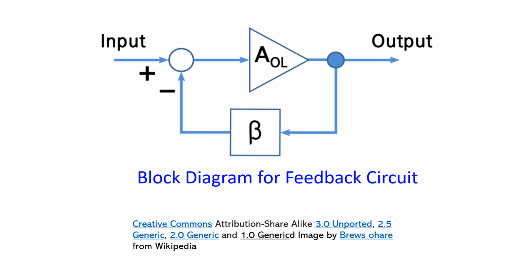Automatic volume control prevents overloading of the receiver when the signal is strong. The average or peak output signal level is used to dynamically control the gain of the amplifiers so that the circuit works well with a greater range of input signal levels.